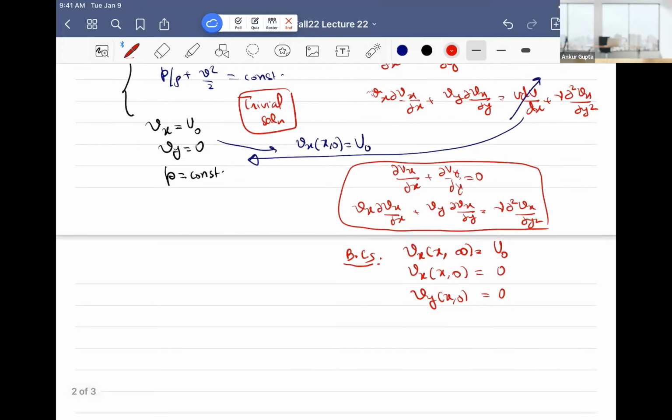So again, I want to emphasize how we got here. Potential flow does not give us drag. We derived the boundary layer equation last time. Now we are saying we focus on a flat plate because it drops off this u du by dx term. And you simply get this equation, and now we have these two equations and boundary conditions. That is how the process goes.